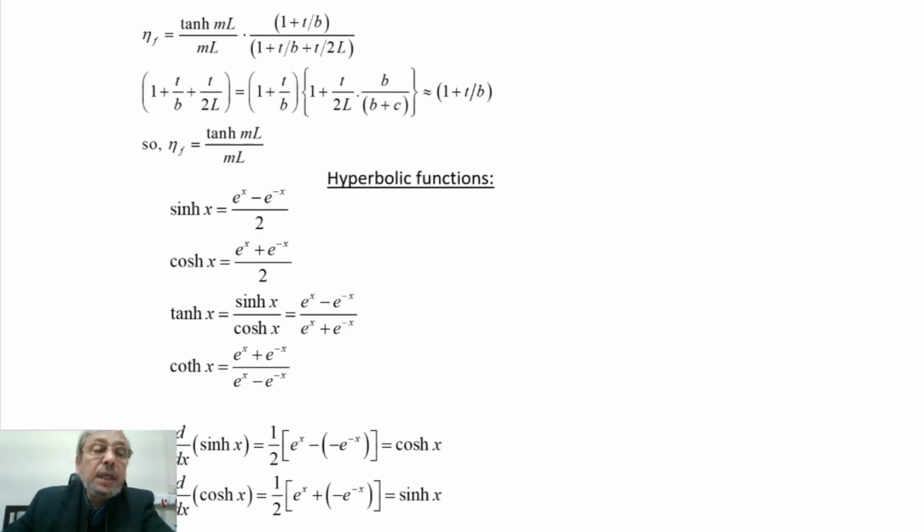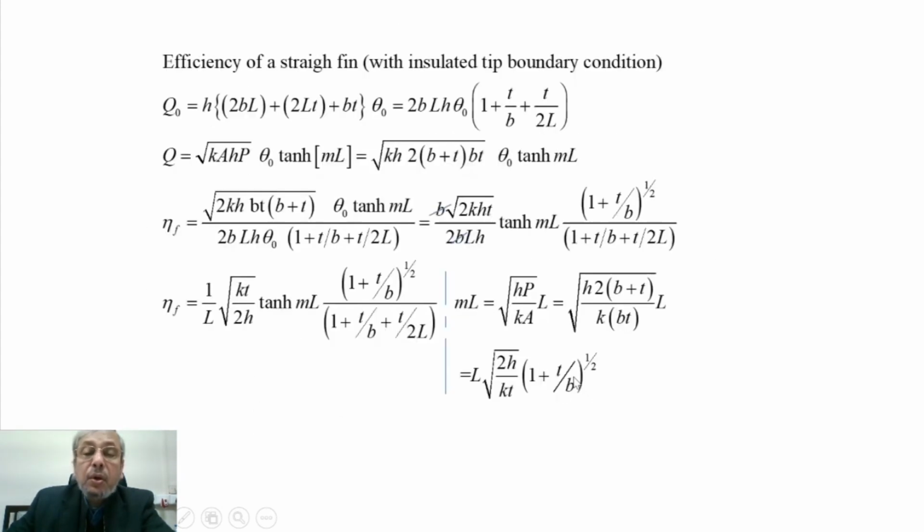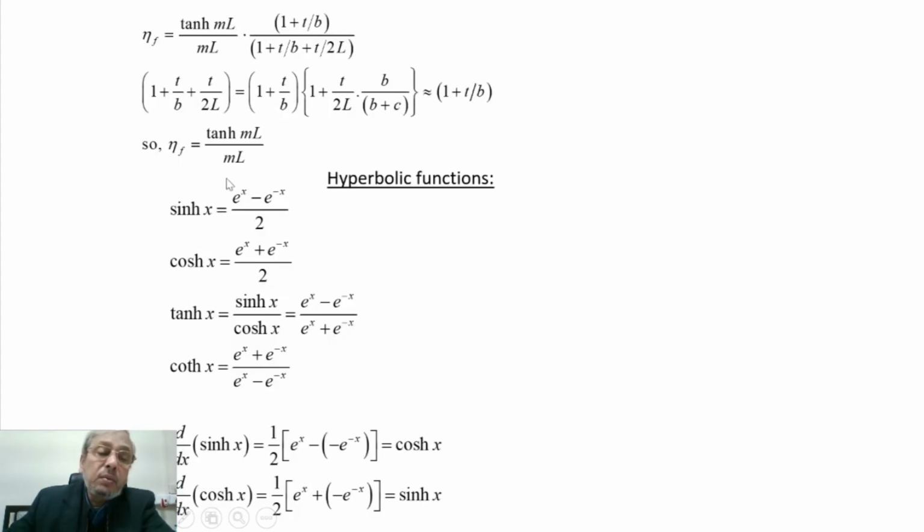And also we have just discussed how fin efficiency can be defined, that is heat transfer rate from the fin surface, actual heat transfer rate, divided by the heat transfer rate which would occur if the entire fin surface was at the base temperature T0. So we got that.